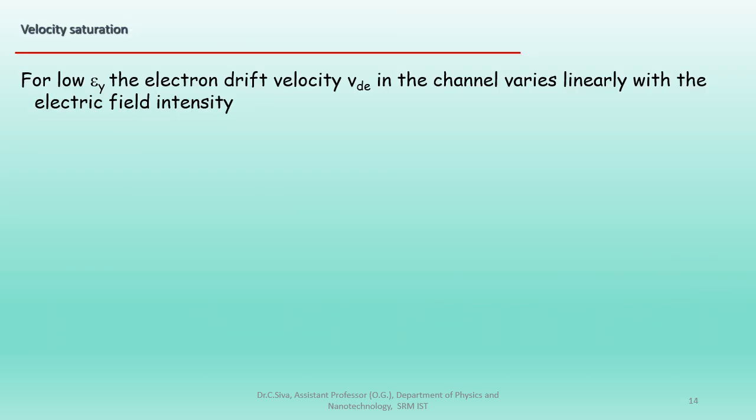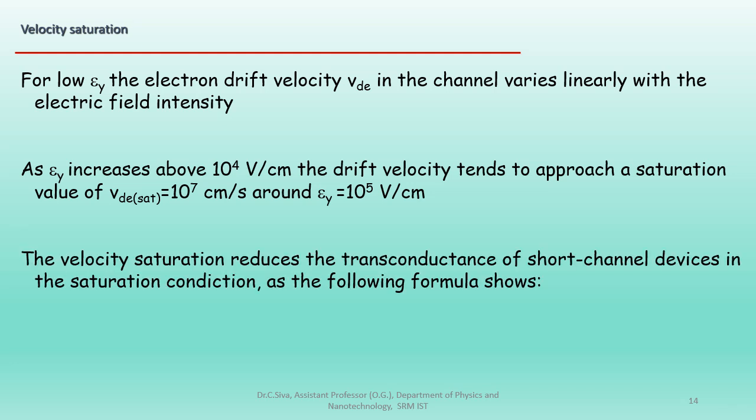The next one is called velocity saturation. At low fields, carrier velocity increases linearly with the field. At high fields, velocity saturates at approximately 10^7 centimeter per second.